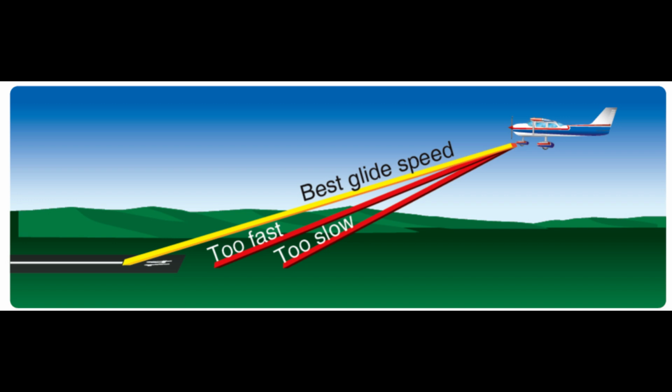This over-control of the aircraft may cause slips and skids and result in potentially hazardous flight control conditions. Some examples of this hazard are: 1. A low-level gliding steep turn during an engine failure emergency. If the rudder is excessively deflected in the direction of the bank while the pilot is increasing elevator back pressure in an attempt to retain altitude, the situation can rapidly turn into an unrecoverable spin.